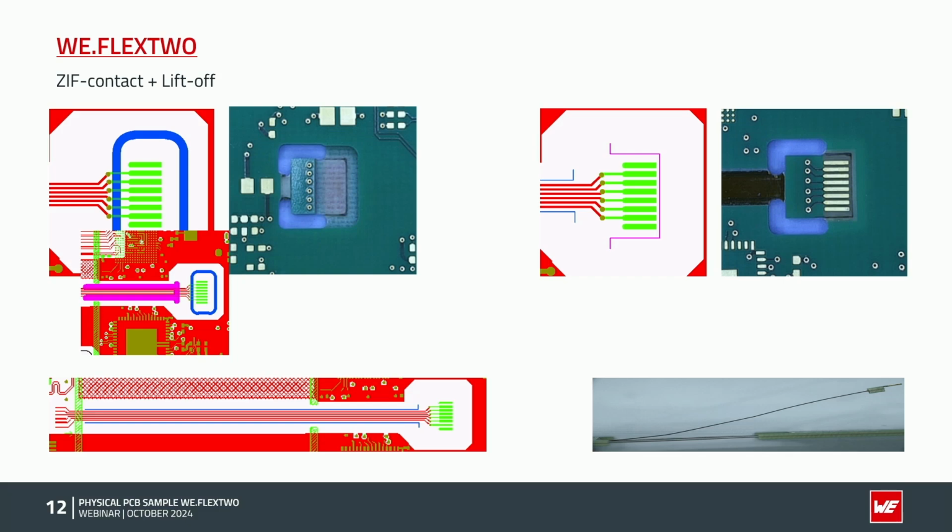So that's not an additional process. If you have the gold fingers on the inner layer, it's quite a complex process which we have to run in production. So the laser tool, the registration on the conductor patterns here, fits very tight to all the outer layers.